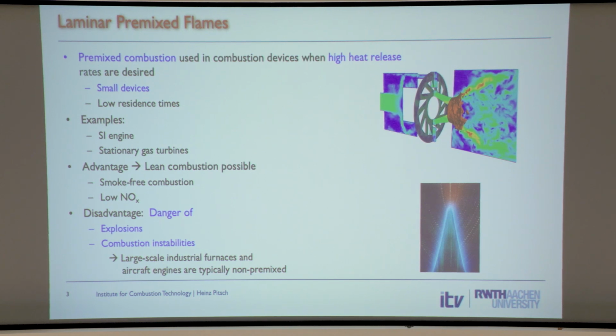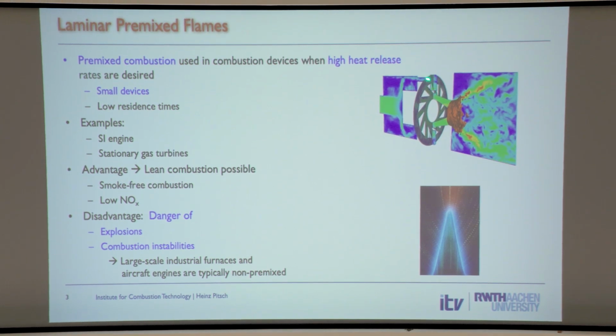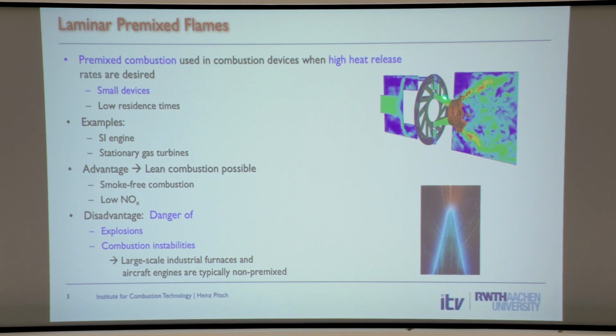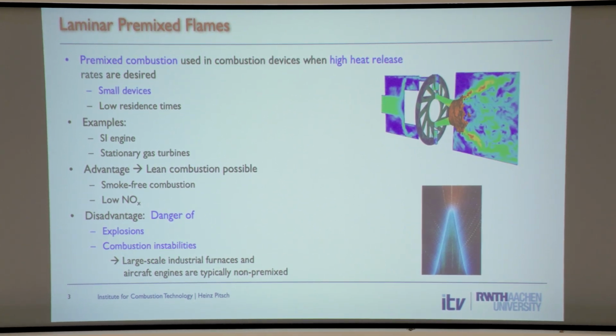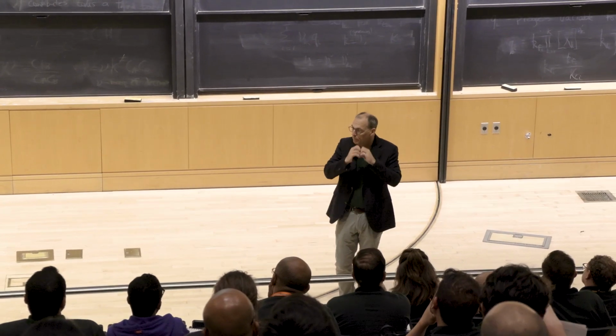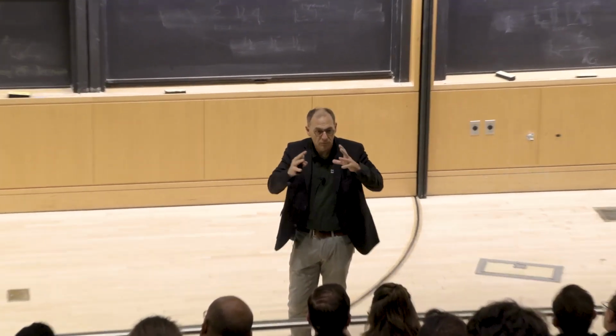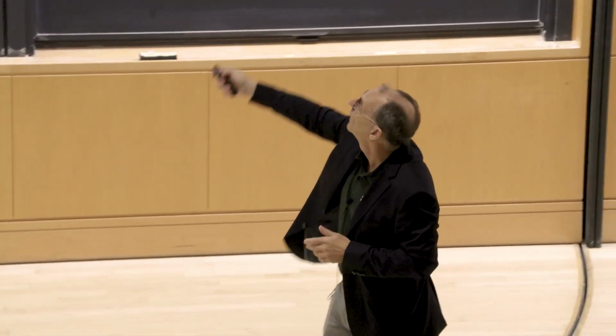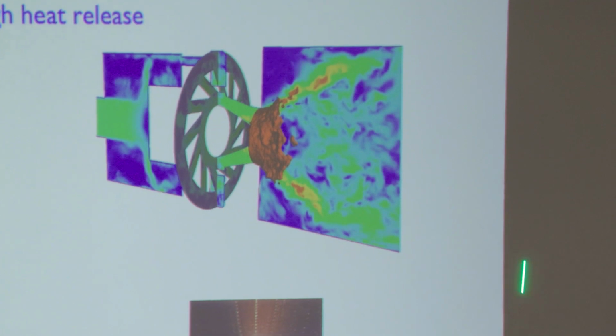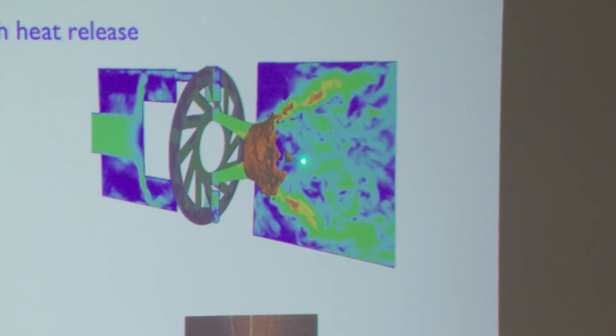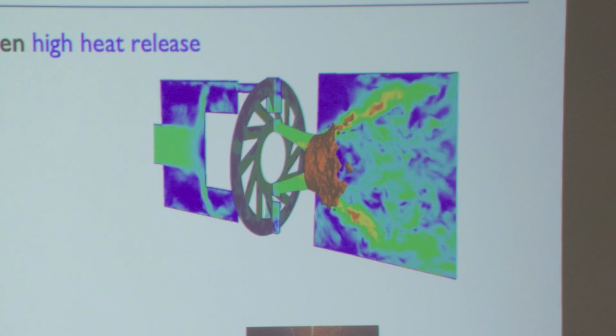What a thermoacoustic instability is, roughly, is this. Think of it like this. Your fuel is added here. Air comes here from far upstream. They mix here and they start burning here. So let's say you have a pocket of fuel and air that comes into the combustor, and then it burns. When it burns, there's a heat release, a volume change, and you get a pressure wave, okay? That pressure wave travels all the way downstream. It's reflected somewhere here at the exit. It comes back, and then it goes maybe through this swirler.